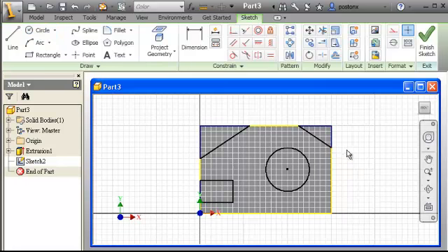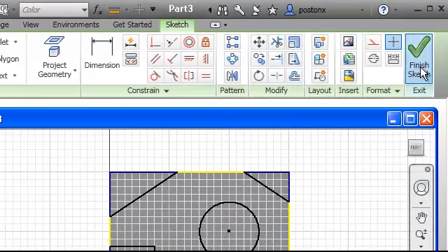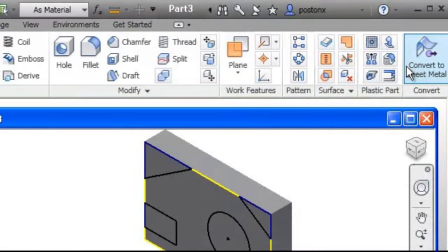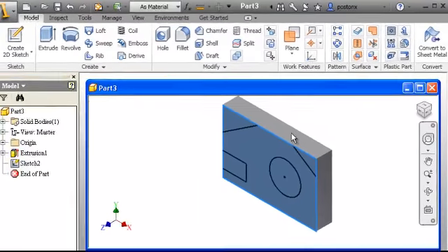Every item on every element, every item is on the drawing correctly, and we can hit escape and drop out. Once we drop out of there, we want to finish sketch. Every time, get done with the drawing, finish sketch. We're finished with it. But now, we got to extrude. Okay, we come over here, and we click on right click, and we go extrude.